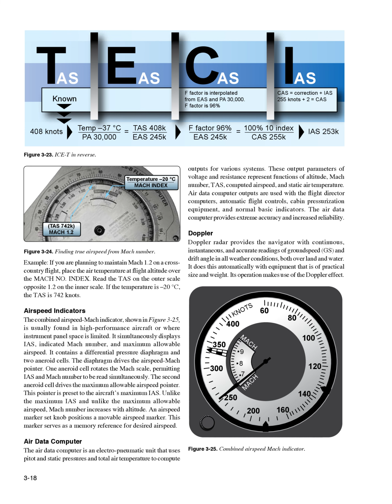Doppler radar provides the navigator with continuous, instantaneous, and accurate readings of ground speed, GS, and drift angle in all weather conditions, both over land and water. It does this automatically with equipment that is of practical size and weight. Its operation makes use of the Doppler effect.